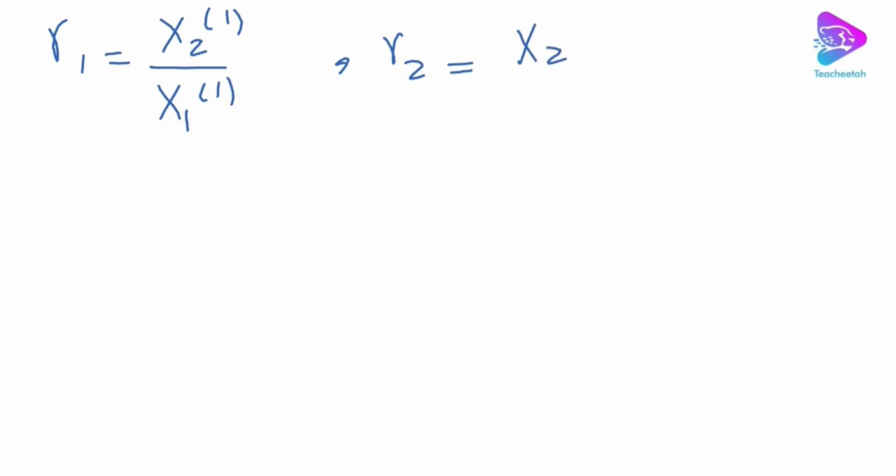R1 as the amplitude ratio for mode shape 1, which is equal to x21 divided by x11. Why we are doing that, you see in the calculation: we get rid of one of the variables, especially for x2 or for mass 2, and then we calculate everything based on x1 and R1, which simplifies our calculation. And we also define R2 as x22 divided by x12.